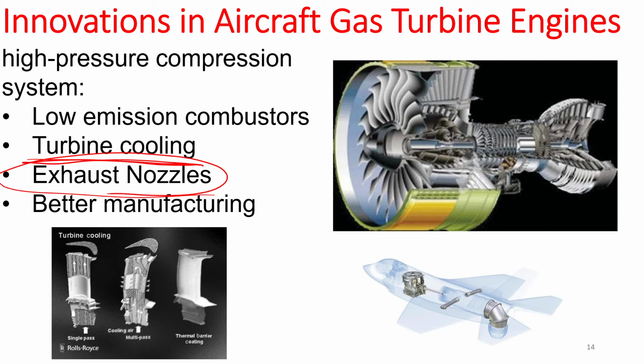The exhaust nozzles, playing with their direction, with the circumference of the exhaust nozzle, the outlet there, is always a very interesting thing and results in very interesting phenomena as well. As you can see, the exhaust nozzle here is geared toward beneath the aircraft, toward the earth, essentially, instead of just exhausting air to the back. This will definitely affect your thrust, right? And it will give you a lot of other controls, like the thrust vectoring. All of these are controlling the direction of the thrust.